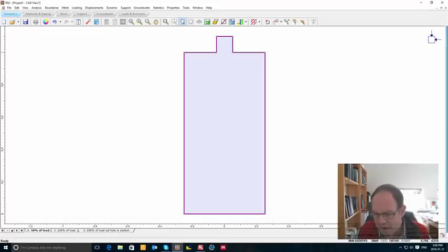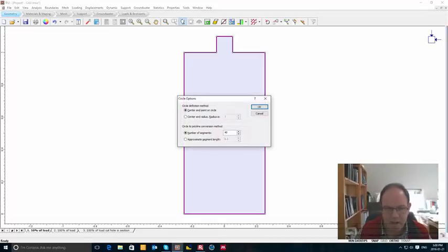And then down the bottom right it gives us options, table, circle, etc. I'm going to type I for circle, and it'll bring up some options here. I want to enter the center plus a radius. And I want the radius of the circle to be 0.15 meters.